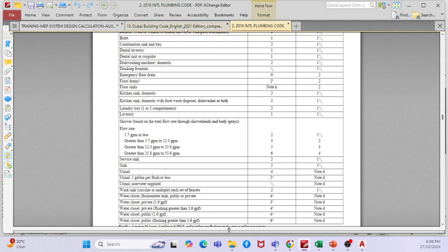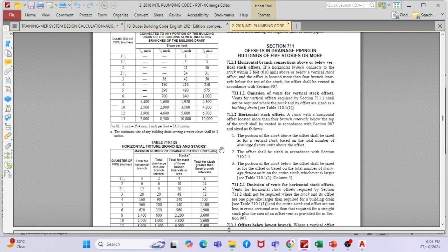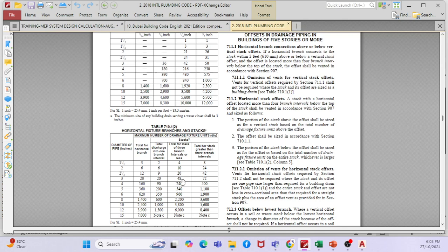Okay. So if I go to the international standard, what is it saying? Say for example, I have 10 floor drains. Assume the 10 floor drains. So 10 into 2, how much? 20, right? So up to 10 floor drains, I can connect with a 3-inch pipe, which is 75 mm, right? But it depends on buildings also, na? Like peak, as we said, every time it will not be occupied. Like peak interval and normal interval of usage.